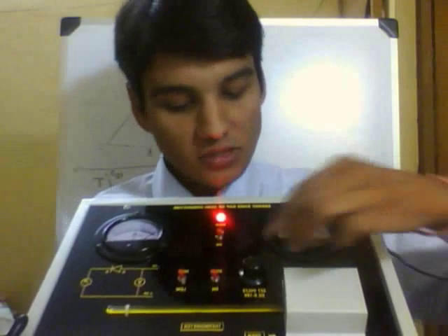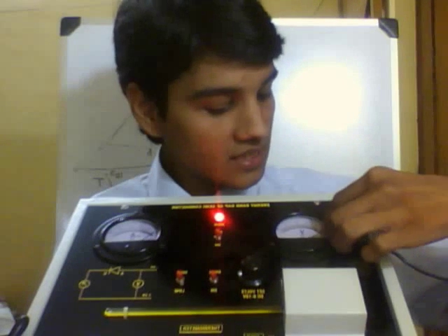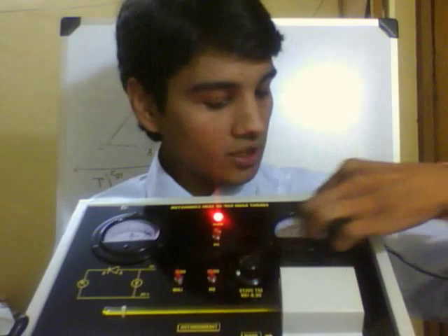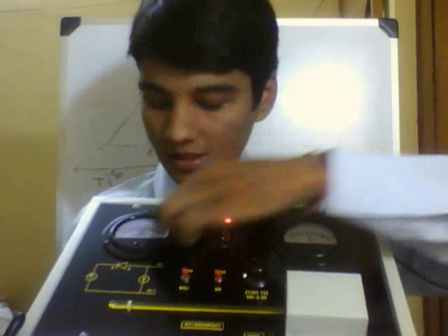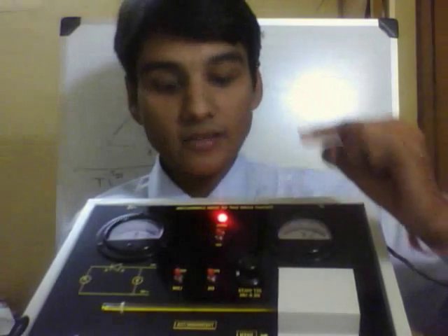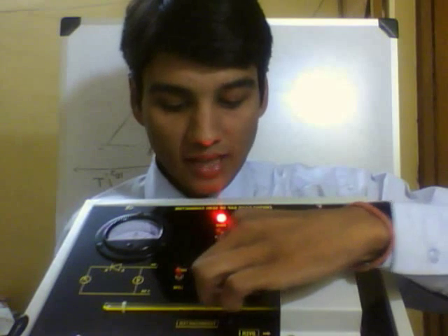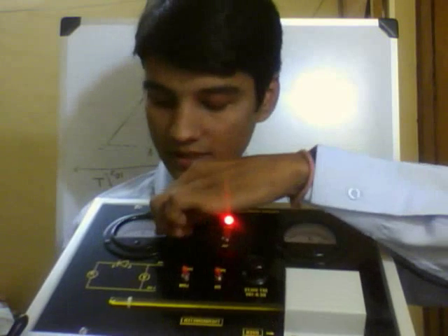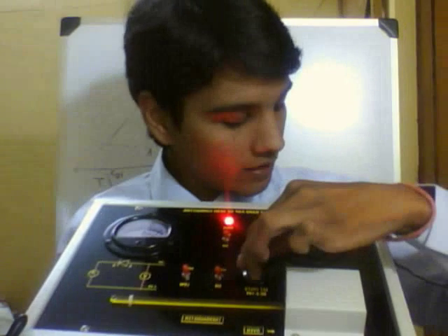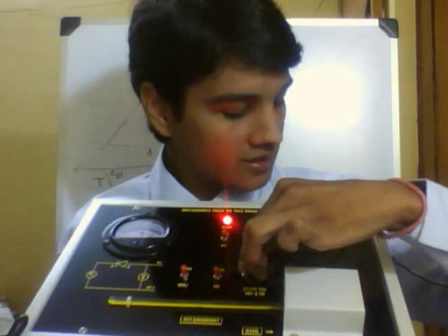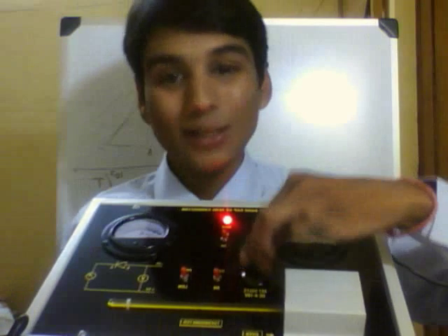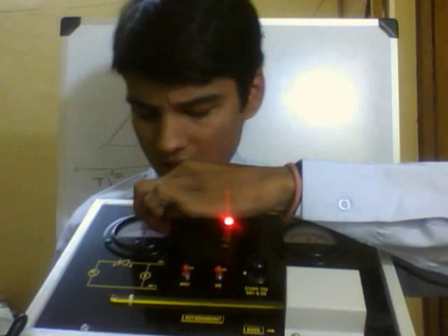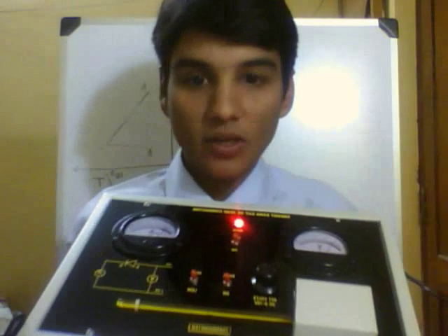As the temperature rises, it will reach near about 40, 50, 60 degrees. As it comes to 60 degrees, the change we see is that whenever we change this regulator, the voltage changes very fast, but the current value increases slowly. But as the temperature keeps rising, look at this: we have turned the voltage to 2 volts, and the value of current comes to about 15 microamperes.